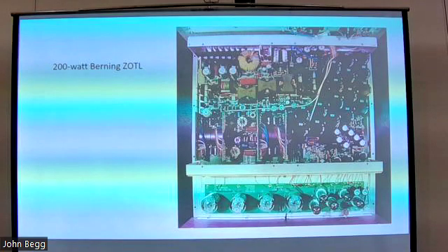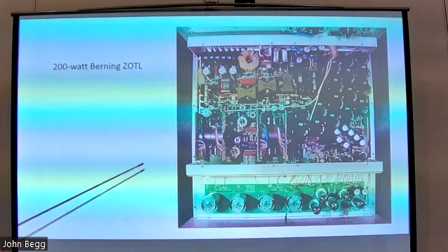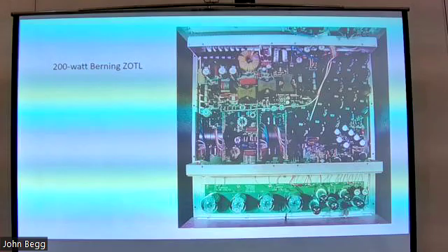It's quadrature. Because of the high power, and that I was charging a lot for this amplifier, there are some non-ideal characteristics of the ZOTL impedance transformation that prevent you from having perfect square waves. I get around that imperfection to a large extent by using what I call quadrature, which is really interlaced power converters. They use this in microprocessor power supplies all the time, what they call interlacing, to get enough current for a microprocessor at low voltage.